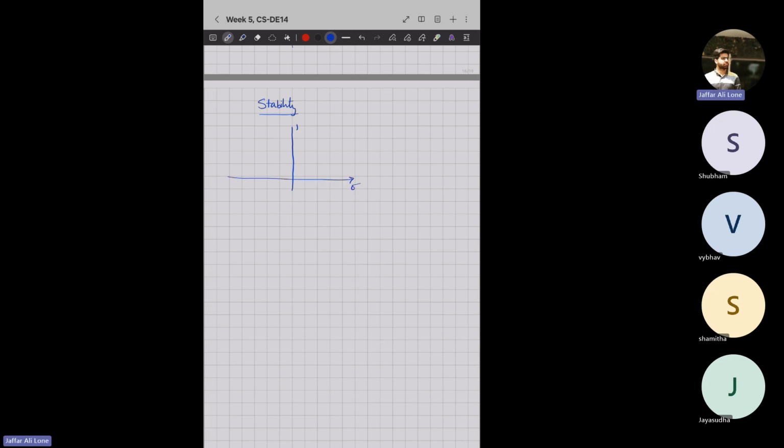This is my sigma, this is my j omega, because every pole, my s, is a complex number which has a real part and an imaginary part. Now I'll plot. Let's assume only one pole. This is the LHP, this is the RHP, and we have the imaginary axis. If you have any pole in the left half plane, then your system is stable, and the graphical representation is when your pole is real.